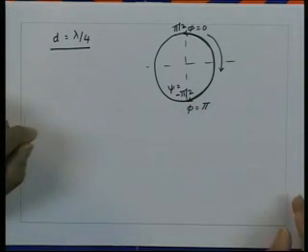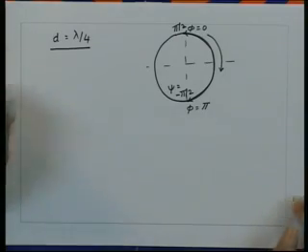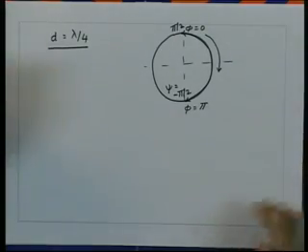So, now for nulls to be visible in the radiation pattern, two things must happen. One, the root must lie on the unit circle. Second, the root must lie in the visible range of psi. Then and only then can we see the nulls in the radiation pattern. Any of the things not happening will not represent a null in the physical space.